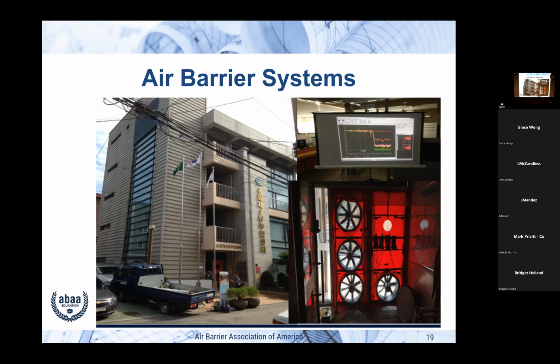Okay, makes sense. The other test is you seal big holes, but things where you have louvers and so on, you close them. So that is not just an energy test, because now we're starting to play with some of the holes. If we got a big hole for an exhaust duct and things like that, we seal that off because that's an intentional opening. We know it's there and so on. And we're trying to find where the air leakage is where we don't know.